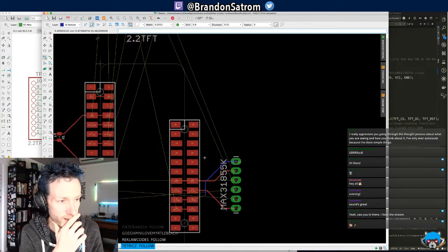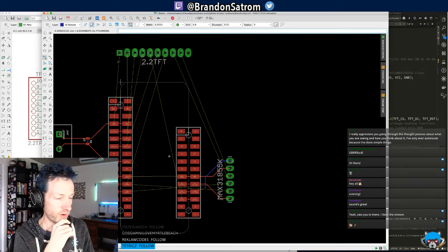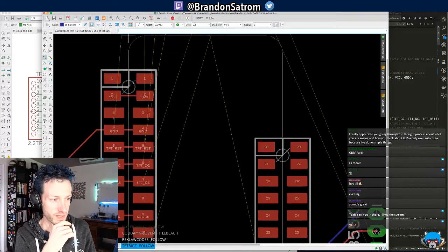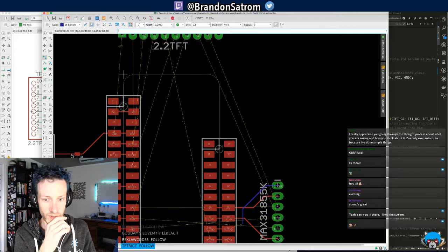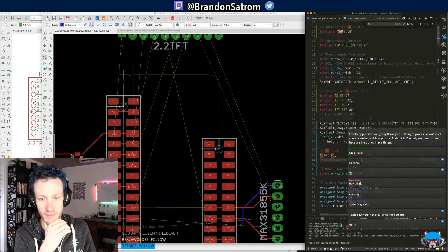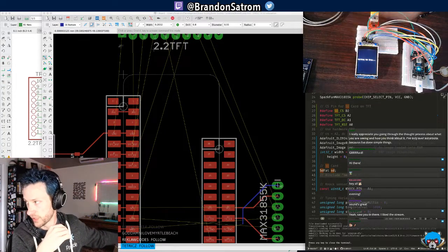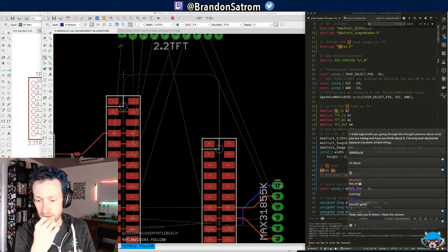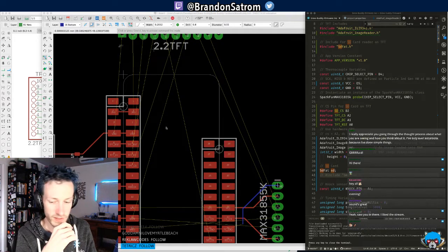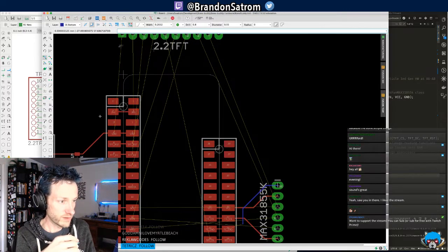So the next piece, and I mentioned before, these yellow lines for folks that haven't done PCB layout before, are basically telling me where I need to route things. They're giving me guidelines to say, hey, you need to actually electrically connect these pieces here on the PCB. These pin mappings I define first in the firmware, and as I showed earlier, this jumper wire prototypey business was what we got working last week. So now it's time to do the fun of creating this custom PCB and wiring things up, and then I'm going to order it online, and should have it on hand in the course of the next week, which should be kind of fun.